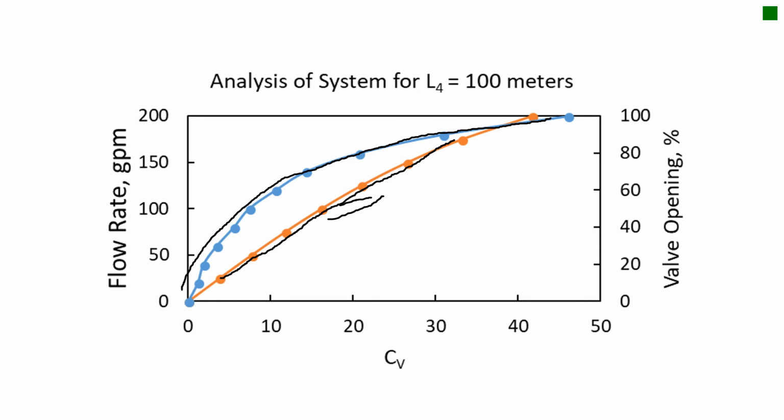You will see some cases where we have large frictional losses in pipelines, especially if we have things like heat exchangers, filters and the like, or lots of fittings or long pipelines. We will find that our system curve, which I display in orange, will start to match the equal percentage valve curve, which is displayed in blue.